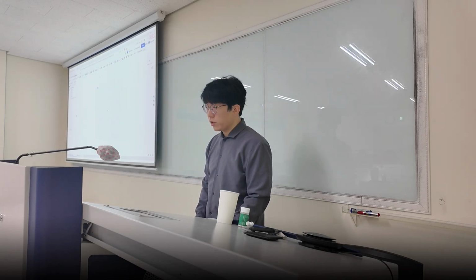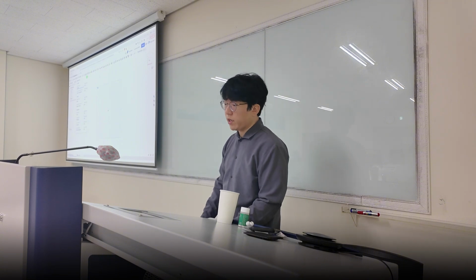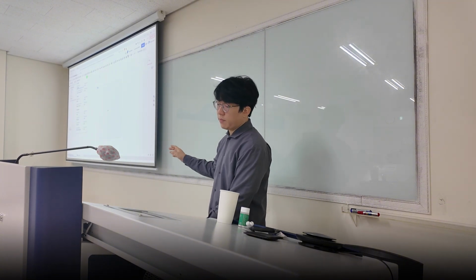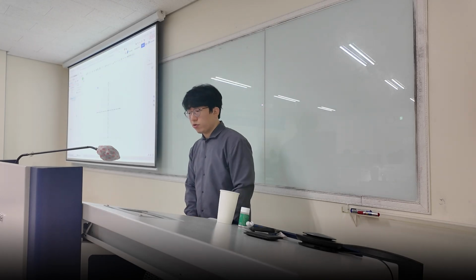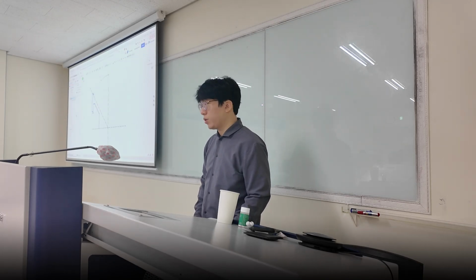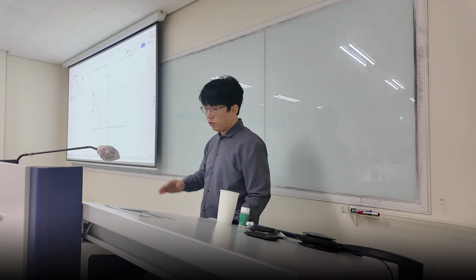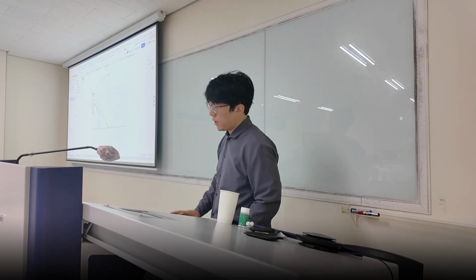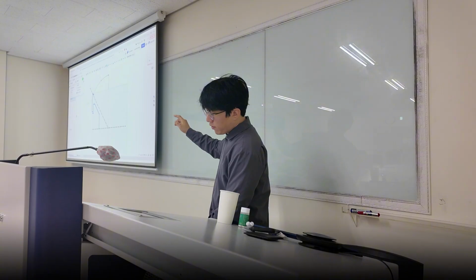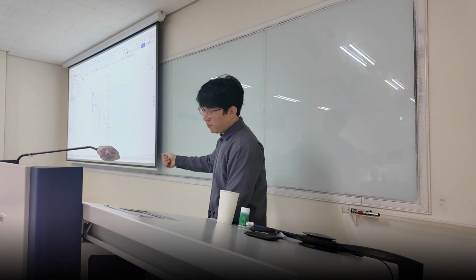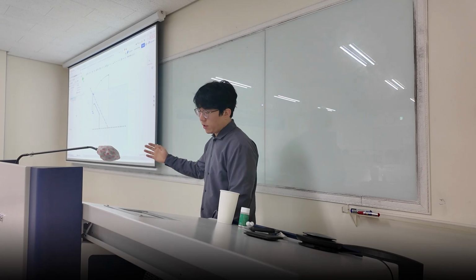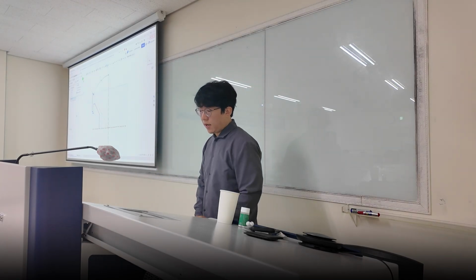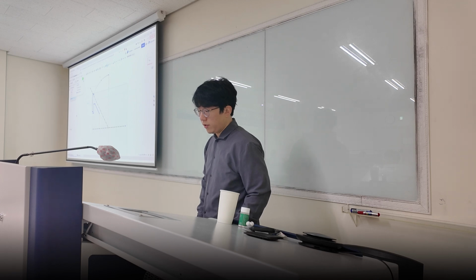Out of these three perpendicular planes, we're going to choose the top plane, and make sure the default length measure is millimeter. Then we're going to draw three construction lines. Because we have construction lines, we can use the mirror function. Once we have the construction lines, we're going to draw something like this, and make sure you have everything without constraints at first, because if you have constraints, you're going to see the lines in black, and you're going to have a really hard time making sure they're properly formulated.